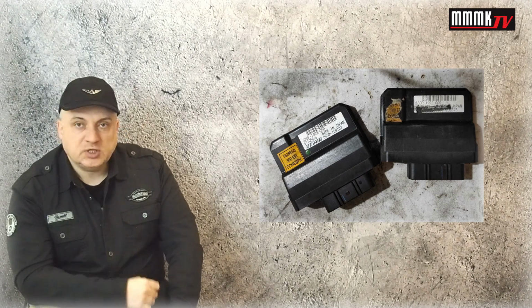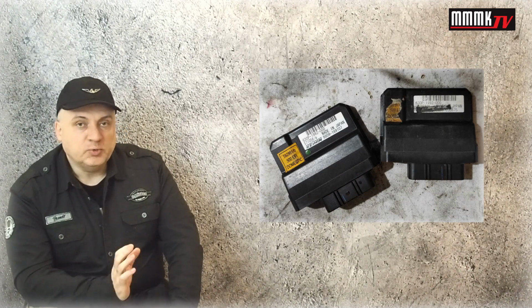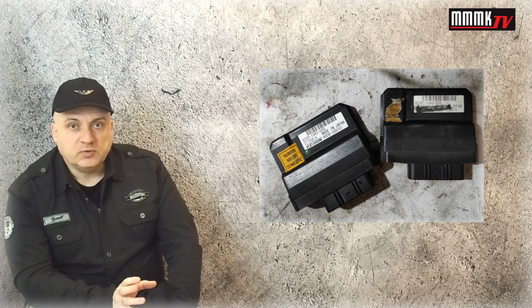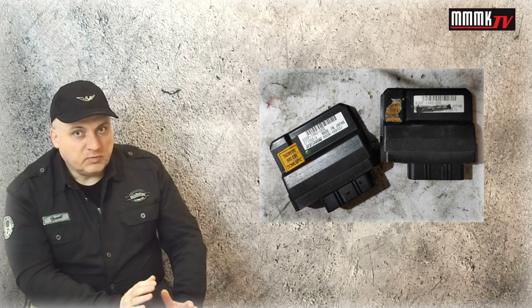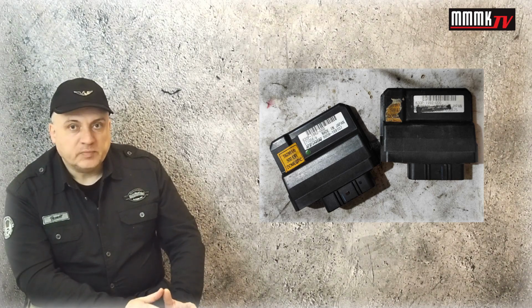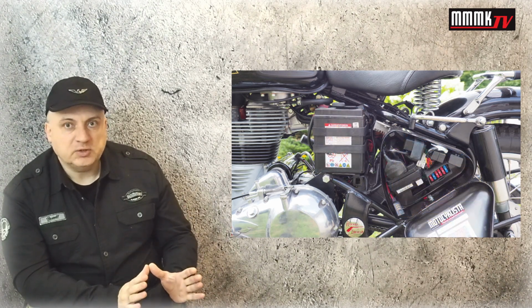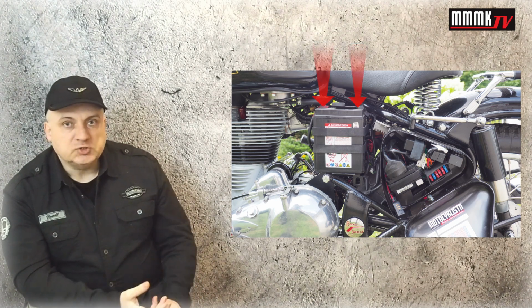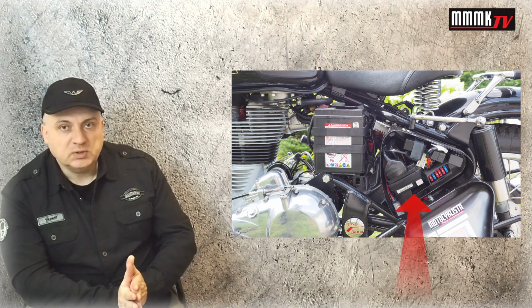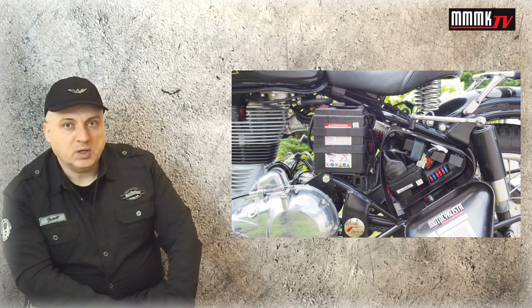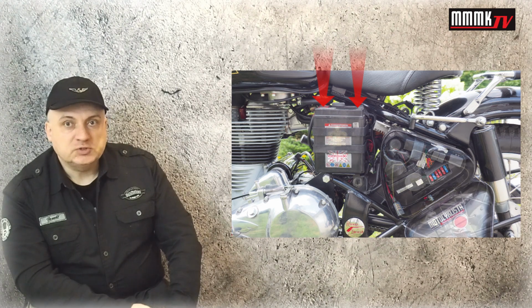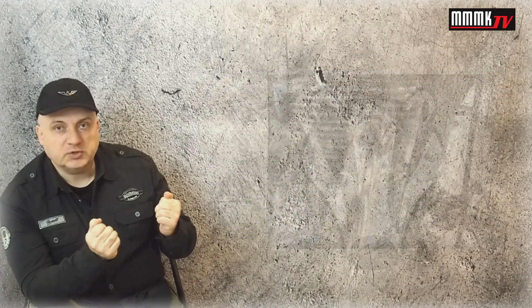So the next stage was to purchase those ECUs and check them out. And this is what I did. I bought two of them, for me and for a friend of mine. So one day I finally got the two of them and we installed them, me and my friend. Here comes one tip: when you replace the ECU, it is very advisable to disconnect the battery completely, unplug the ECU, plug in the new one, and then hook up the battery again. And of course I disconnected the O2 sensor connector.